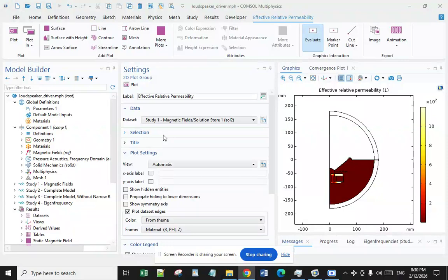The AC current in the electric coil generates eddy current on the surface of the material. According to the theory of electromagnetic induction, the eddy current is distributed only in a very thin layer of the material called the skin depth. This depth reduces with the increase of AC frequency, material conductivity, and permeability. Typically for 1 MHz AC excitation, the skin depth is only a fraction of a millimeter for primary metals like steel, copper, and aluminum.